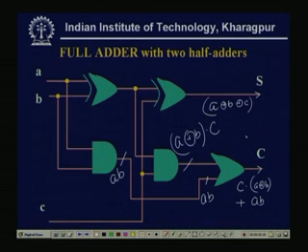Now, there can be many other realizations possible for this full adder circuit. Again, what we have discussed for the half adder circuit is true here, that it depends on what type of gates are available for my realization. That can be the traditional AND OR gate realization, or multi input gates, even with AND OR gates it can be multi input, or 2 or 3 input gates, or the XOR XNOR gates, with the inverters also may or may not be there. With that realization it is possible.